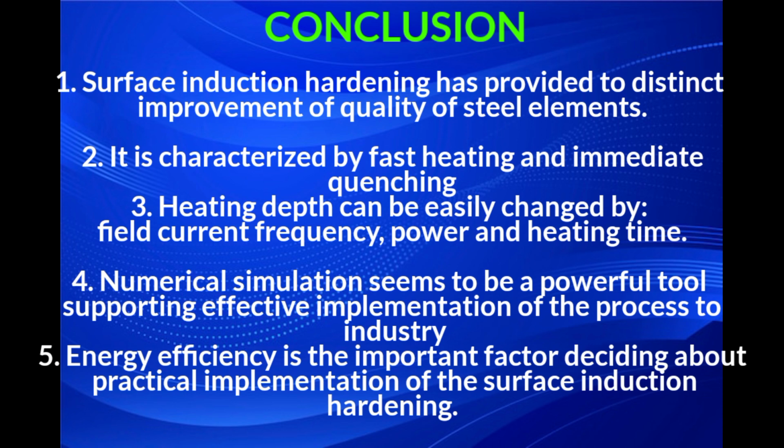So now we will conclude. Surface induction hardening has provided a distinct improvement in the quality of steel elements. Second one, it is characterized by fast heating and immediate quenching. Third one, heating depth can be easily changed by field current frequency, power and heating time. The fourth one is that numerical simulation seems to be a powerful tool supporting effective implementation of the process in industry. And the last one is that energy efficiency is an important factor deciding about practical implementation of surface induction hardening.